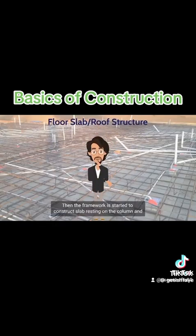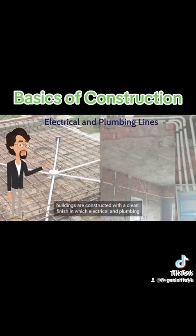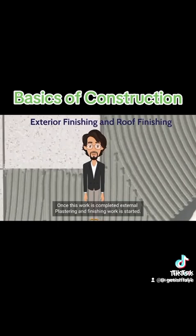Then the framework is started to construct the slab resting on the column and beam. It is done as per the slab detail drawing. Door and window frames are fixed at specified positions as in the drawing. Buildings are constructed with a clean finish in which electrical and plumbing work is not visible. They are installed in the walls and slabs such that they are concealed and not visible after the finishing work is done. The point and pipe end are left out, such that later they can be finished with the electric fitting and plumbing fixtures. Once this work is completed, external plastering and finishing work is started.